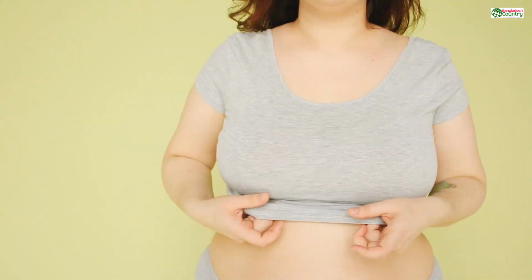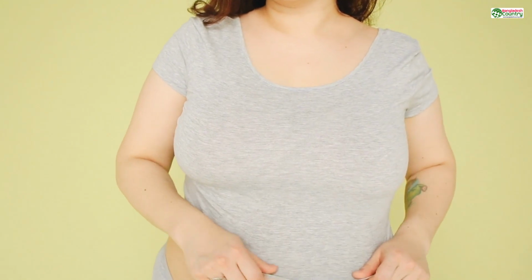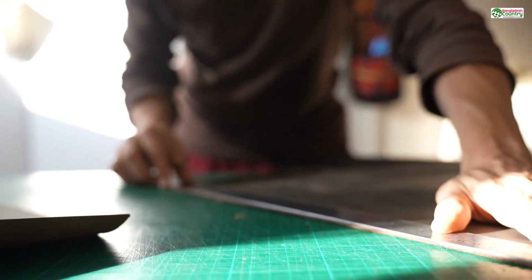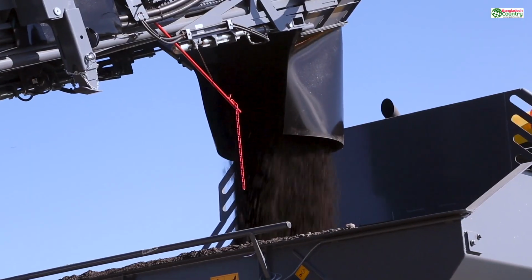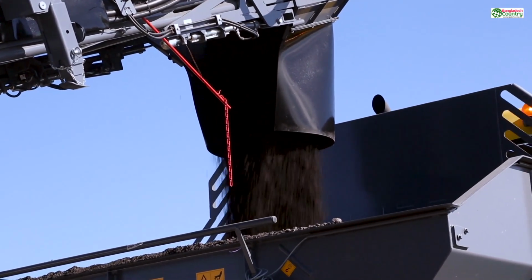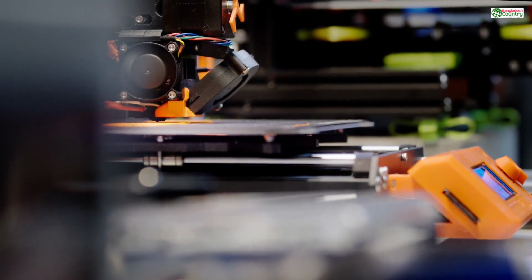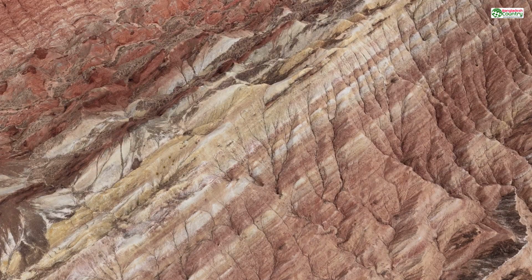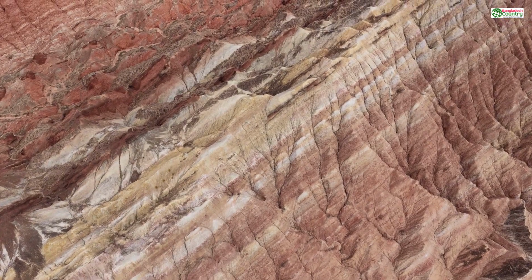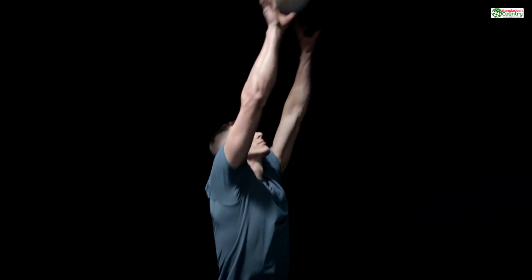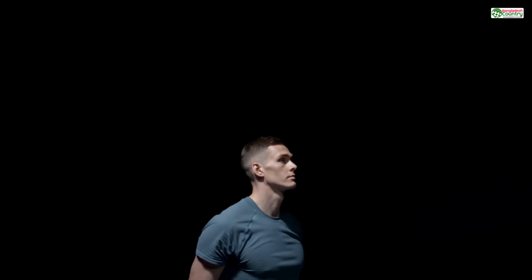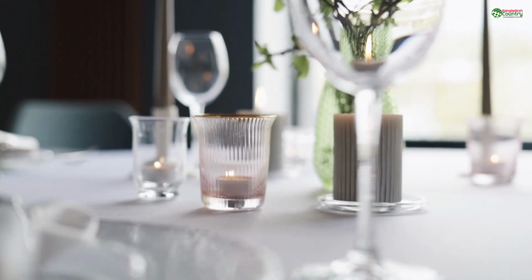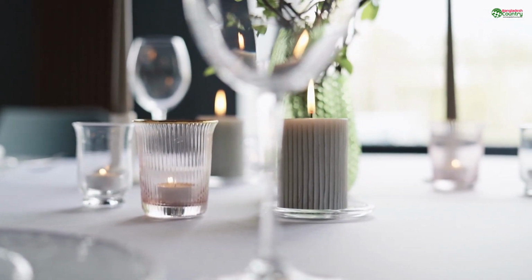The machine is laying down one sheet of melted plastic at a time. The layer height setting tells the printer the exact thickness of each of those sheets. A common layer height might be 0.2 millimeters. For reference, a standard sheet of office paper is about 0.1 millimeters thick. So we're talking about building your object 2 sheets of paper at a time. This single setting creates the most important trade-off in all of 3D printing: the eternal battle between quality, speed, and cost. You can pick 2, but it's very hard to get all 3.